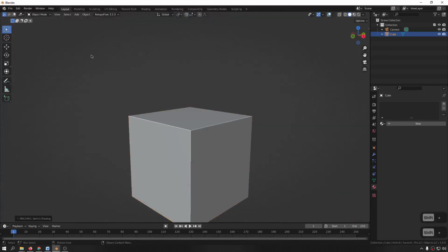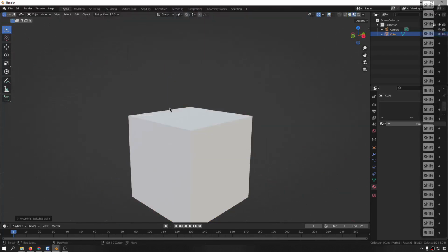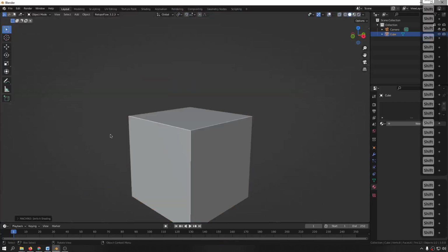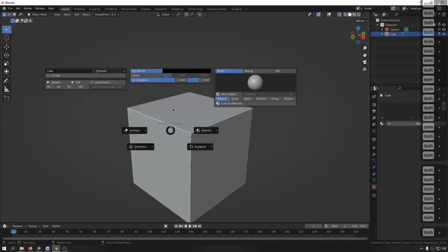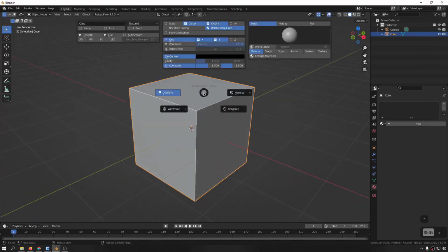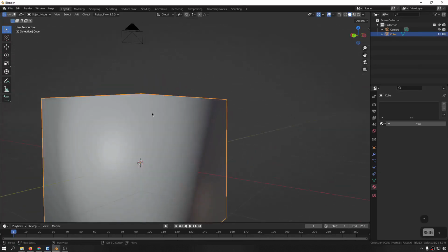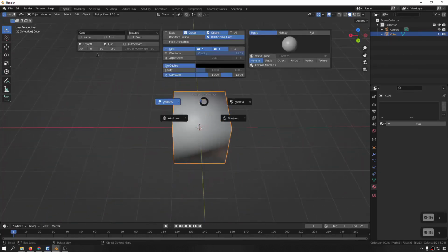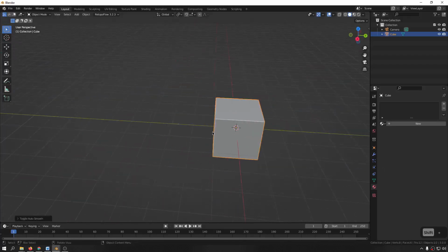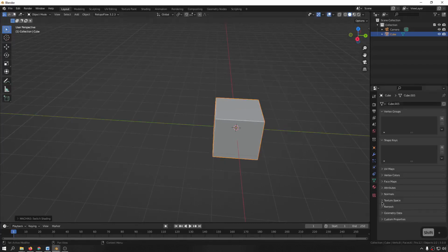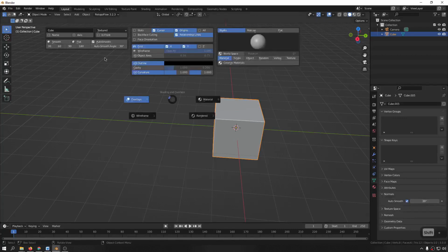For example, if we want to check for the face normals to see if they are working or not, or if we want to set it to material, rendered, wireframe, or solid, or basically whatever you want to do with it. And one good one is shade smooth, which basically shades the whole thing as smooth, and one is assigning a degree for smoothing, for example, for something hard surface. And this basically does what this one does in here. You really do not have to come in here and shade smooth and correct the normals, but you basically come in here and select what you want.